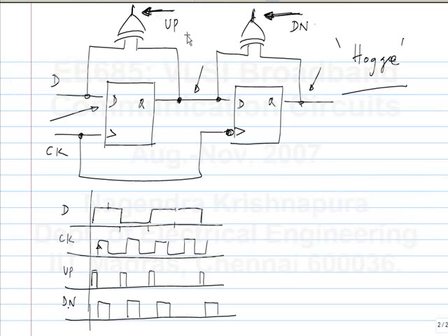So the clock and data recovery circuit is crucially dependent on the number of transitions you have, right? Can you have a transition density that's very low? If you have no transitions at all, there is no meaning to a clock and data recovery circuit, right? So what happens when the transition density is low? By transition density, I mean the best transition density is when you have a 1010 pattern. Of course, that is useless data. If you already know it's a 1010 pattern, you can generate it for yourself. There is no need to transmit that thing.